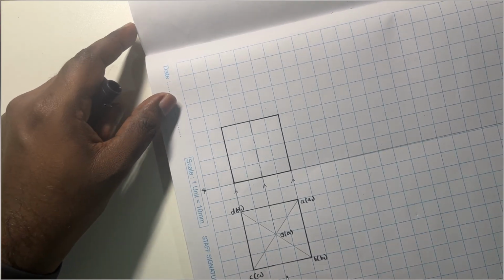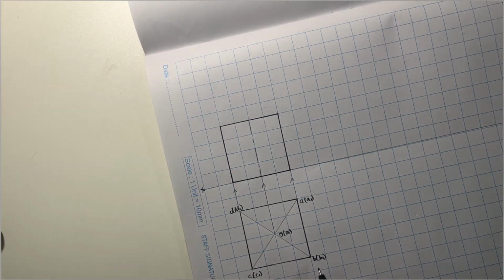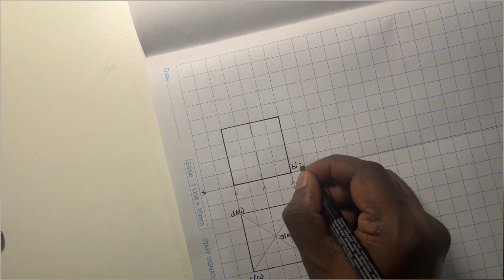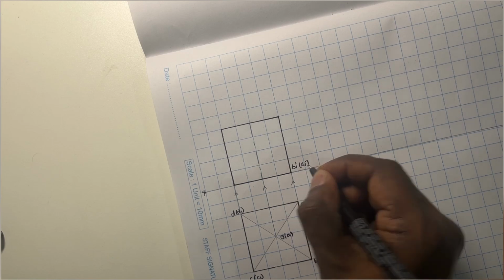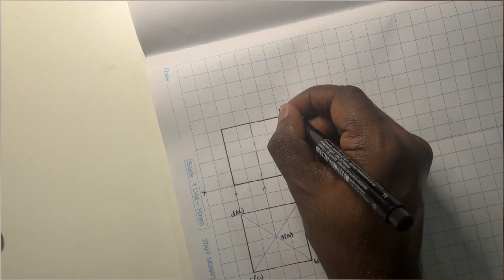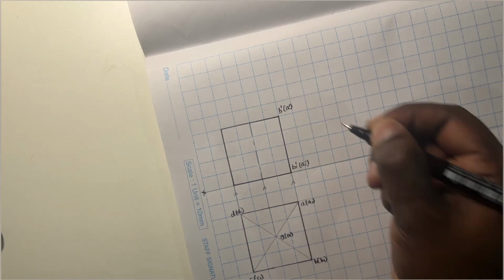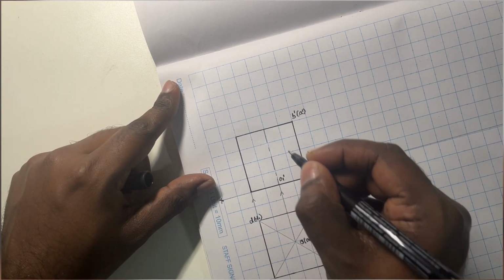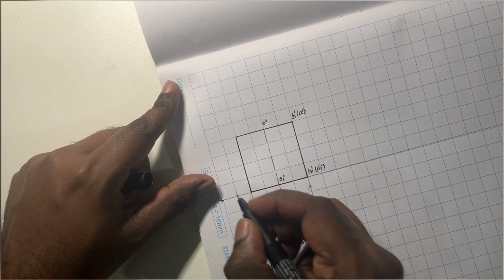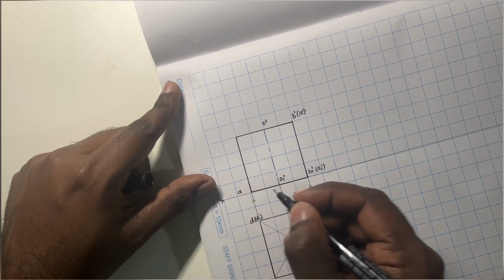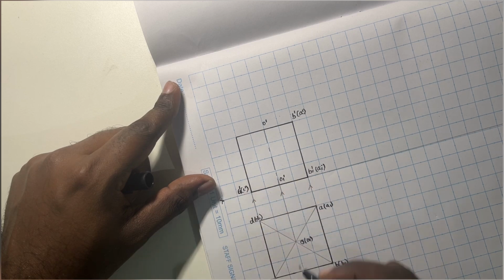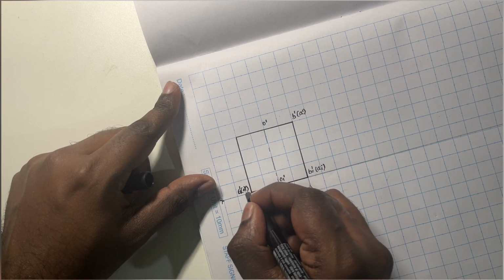So the observer is going to look from this direction, and for him the corner B1 is visible first. So it is B1 dash, and inside the bracket it is A1 dash. Similarly, the top faces B dash and A dash. And coming to the axis, this is O1 dash and this is O dash. And similarly, this corner here is C and then C1 and C dash, C1 dash and D1 dash.